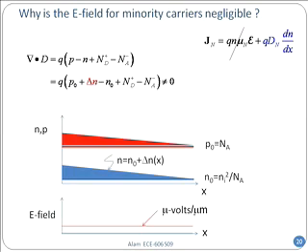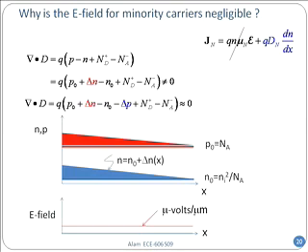Now, do you see here that this region is almost charge neutral at every point, almost. But it's not density neutral at every point. The density is no longer the same, right? At every point, density is non-uniform, but charge-wise, it's essentially more or less the same. And as a result, that delta P flowing in from the contact is almost equal to 0.